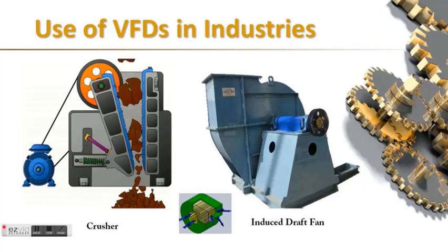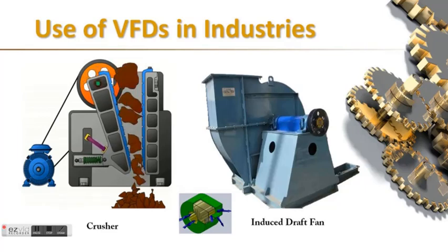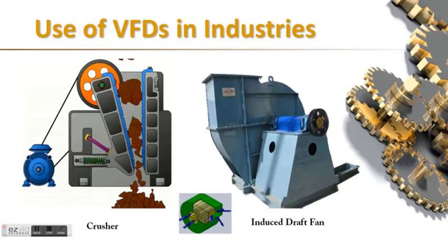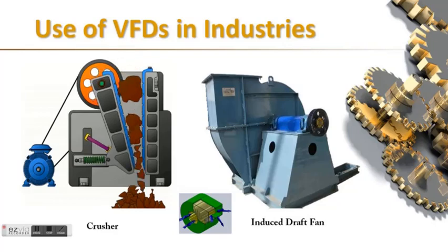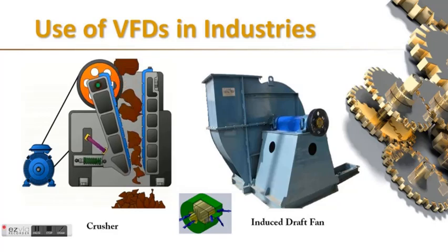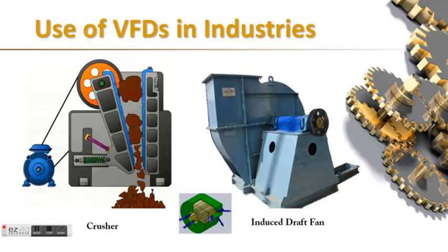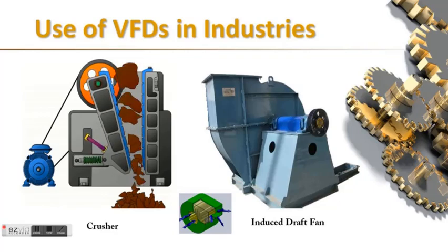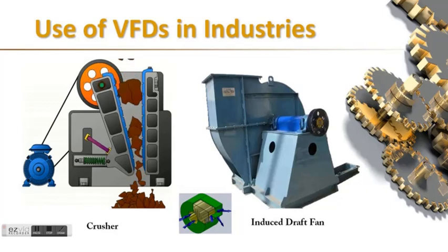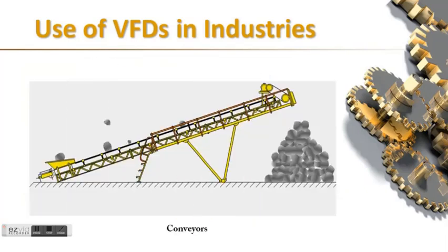As induced fan power can be several thousand HP, using drives can reduce power consumption in controlling airflow. During the cement making process, meeting the required conditions, such as airflow, is essential. VFD effectively manages to run induced draft fans at a specific RPM in such a way that it matches the required airflow.